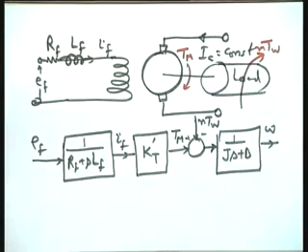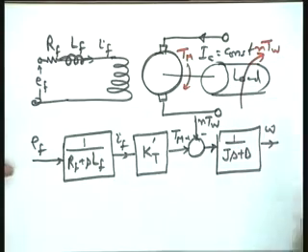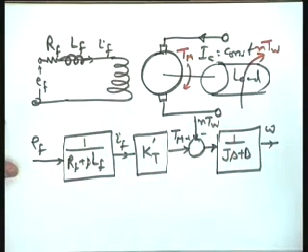You will please note that in this particular case the so called electric friction effect is not available. The electric friction effect, the damping effect you had in the armature controlled mode, is now not available, you are controlling it through the field current. And in this particular case the mathematical model, one more point, turns out to be a third order model.